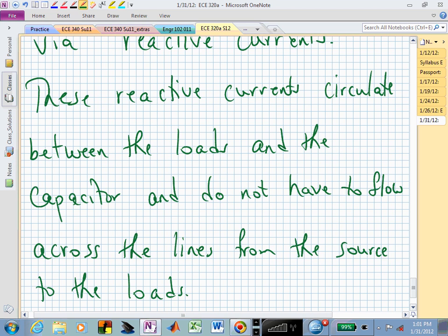Yes? Since we lowered the current, the question was, since we lowered the current, we effectively lowered the power. That's correct. Now, if you looked at the apparent power from the source when you didn't have that capacitor in place, and now I've forgotten, maybe you have it in your notes. What did we calculate I sub G, the magnitude before? I was thinking of that when I was lecturing, and I forgot what we had done before. I'm sorry? So we went from 184 amps to 144 amps. That's a significant difference between the uncorrected and the corrected version of the load.